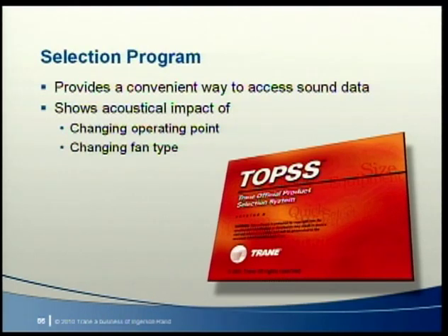John gave an example of this when he compared the performance of an airfoil fan in housed and plenum configurations. In his example, adding a lined plenum section to the housed airfoil fan resulted in considerable reduction in sound leaving the unit. These two developments eliminate the need to rely on rules of thumb to choose one fan type over another. While a rule of thumb can provide general guidance, it can also have exceptions and might only apply to some applications.